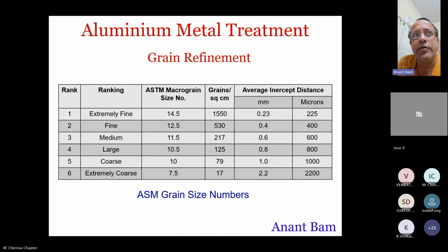Whenever there is a fracture, it's dislocation of grains on a grain boundary. The energy required to dissociate or dislocate a grain from its boundary is called slip energy. That slip energy is a function of that particular alloy system, and it remains constant irrespective of the grain size. So if you say a 10 mm diameter test bar has 1000 grains, then to break that test bar, it will take 1000 units of slip energy.